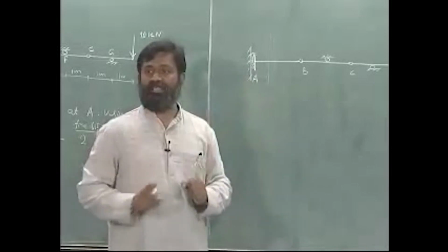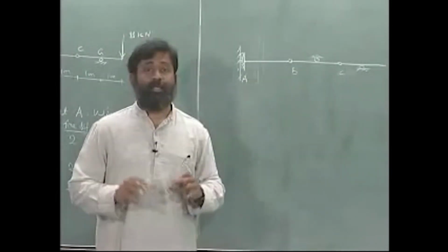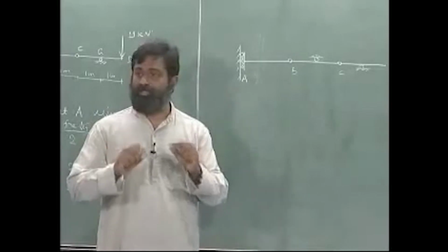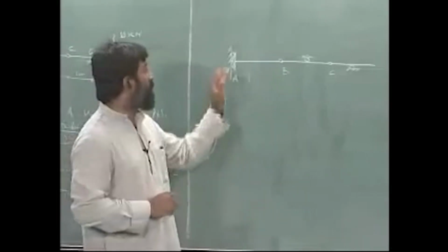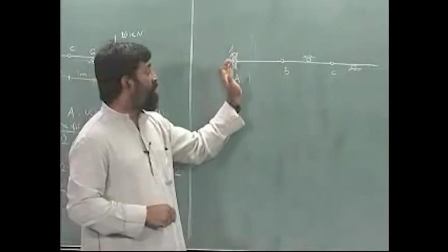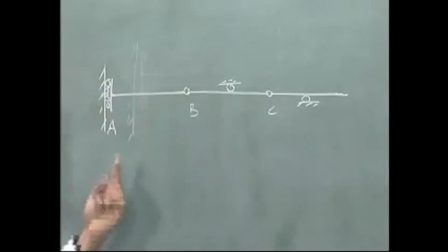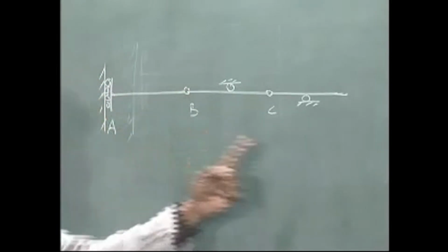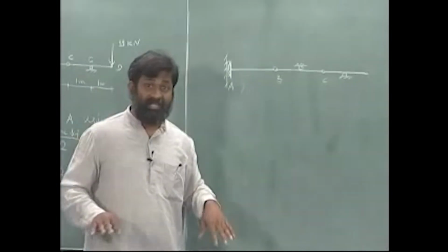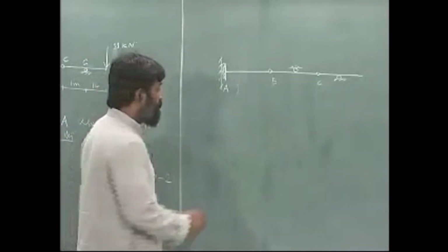The only condition I have to impose is a kinematically admissible virtual displacement. For example, I cannot opt to make a rotation over here, I cannot say okay I will put a virtual rotation and find out. Please remember it has to be consistent with the support conditions as well as the notion of rigid body, okay.